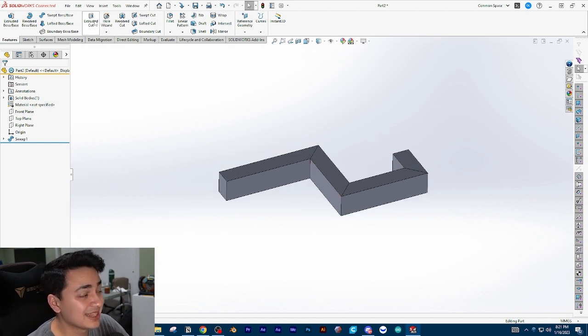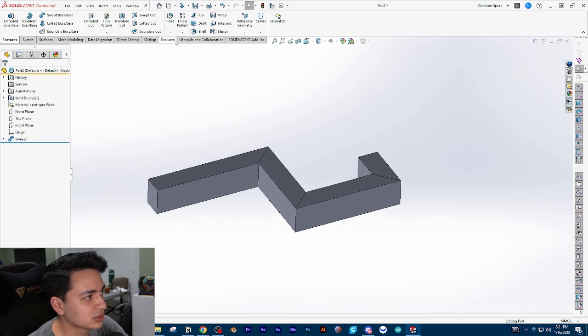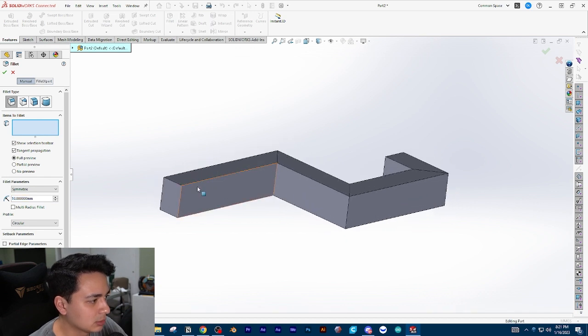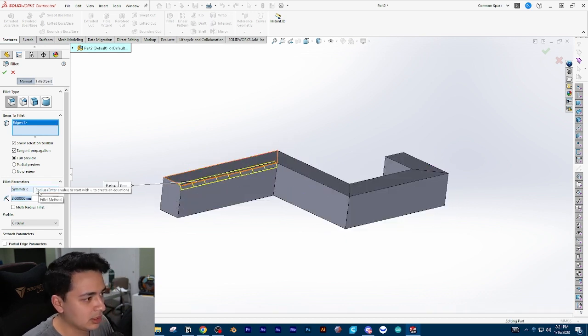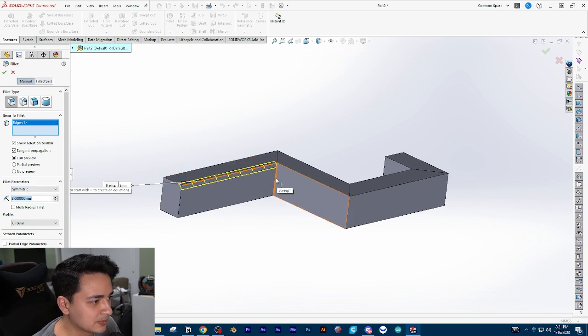And then there's basically the opposite of all of those shapes if you want to take away, right? So if I wanted to make a little hole or something like that, you could use extrude cut. This is just a very high level description of all the features. There's also fillet. This is super useful. It adds a little round, which is super useful for 3D printed parts. It really makes things look nice.